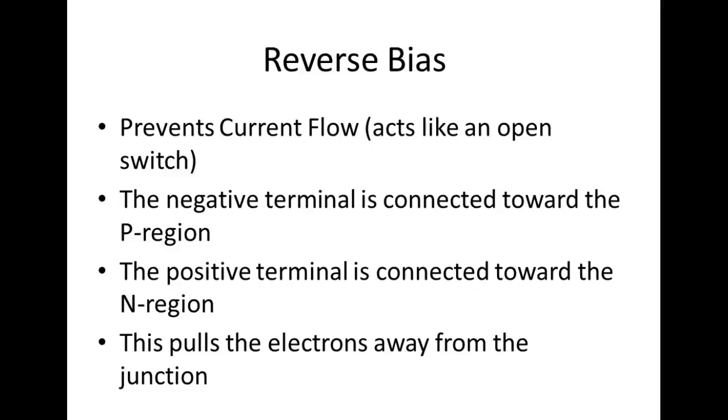If you have a path between point A and point B, then current is going to flow. It's just that the current will be so small that we can't measure it. We're going to measure it. But to measure it, we're going to reverse bias the thing and put like a 10 gig ohm resistor in series with it. So we can measure that voltage drop, and then we can measure nanoamps, right? You understand, because we'll have such a big voltage drop.